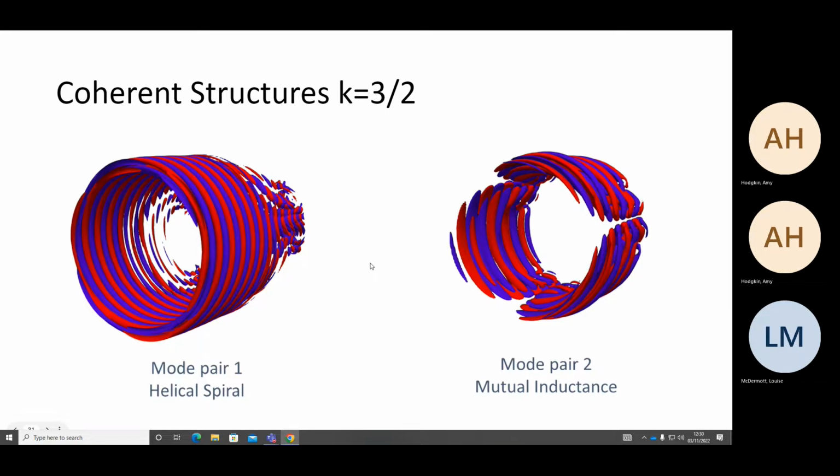So what you can see here is the first mode of the first two most dominant mode pairs, and these are very energetic compared to the rest of the modes for this setup. They take up about 80% of the energy. It's a very simple setup with just our turbine and one perturbation, so 80% of the energy in two modes is a lot, but as expected, I guess.